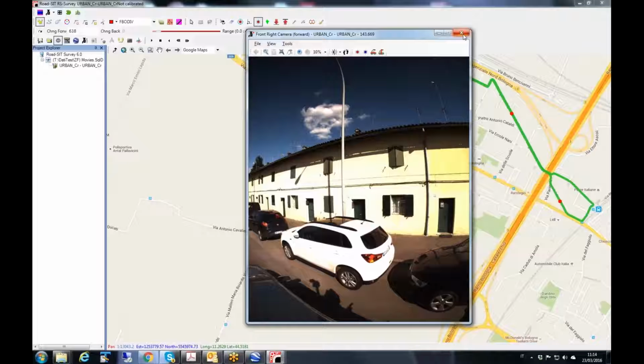Yes, you can go on the roof with the Ladybug and make some stereo photogrammetry survey. You must take care to have some common data from the point cloud on the road and the photogrammetry on the roof, and after link it as a ground control point. You can do it, but it is not included in a normal survey of our system.